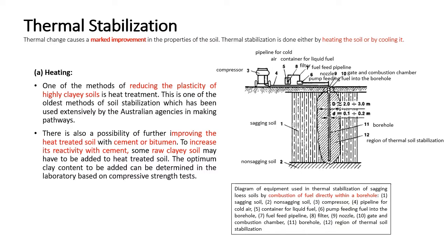The study shows that the soil becomes non-plastic after being heated to about 500 degrees Celsius. Depending upon the method of burning, this will always be a mixture of pulverized soil and clods after heat treatment, which give a good gradation. The CBR values of this material after 4 days soaking would be of the order of 110 to 140%.